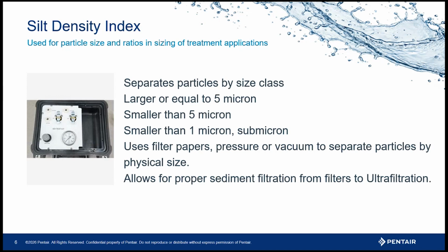Tannins may be reduced by activated carbon. Smaller amounts of tannins don't necessarily require anion exchange if the water chemistry is right. Tannins may also be reduced and removed by anion exchange. And typically, the higher the tannin amounts, the more you're going to look towards a solution like anion exchange.